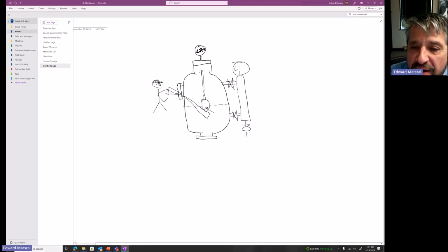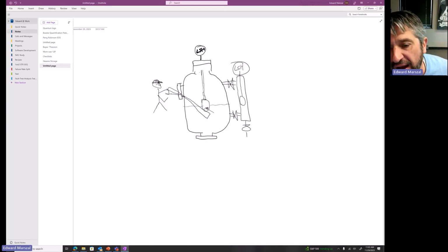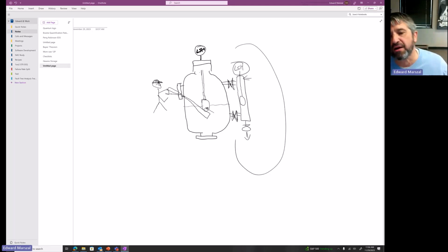It would be better if I had my level switch on this external bridle, because then if I want to test it, I can simply isolate from the process, drain the liquid out, and then put liquid in the top and fill it up to the trip point and make sure that it activates. So this method over here is infinitely better, much more testable, much more maintainable. A direct level measurement inside the vessel, you're just asking for trouble.